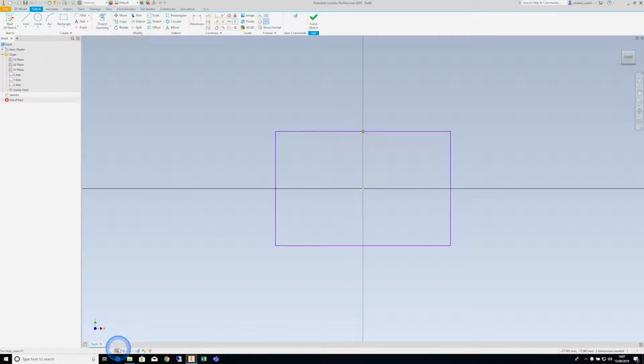The best way to confirm it is to use this little icon down here, and that will switch on and off the visibility of the constraints. I usually toggle it on and off a couple of times. You can use F8 to do that as well. But that will show you all the different constraints that have been applied to this model, whether you applied them or whether they were inferred from the snapping mechanism that's built in.